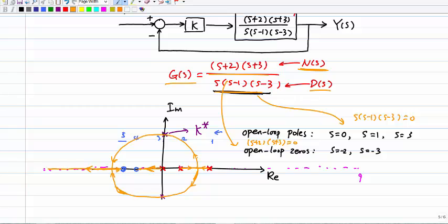So this one, starting from the poles, it must go to a zero, right? You can see this must split. It should go somewhere, then go to the zero, right? Of course, the other one will go to infinity. This is what's happening. So I must split at a certain point, because also they must be symmetric. One of the rules says they must be symmetric. So they must start to merge here, then go to the zero. Otherwise, this wouldn't be starting from a pole and ending at a zero. We see it's starting from those numbers and ending at this.